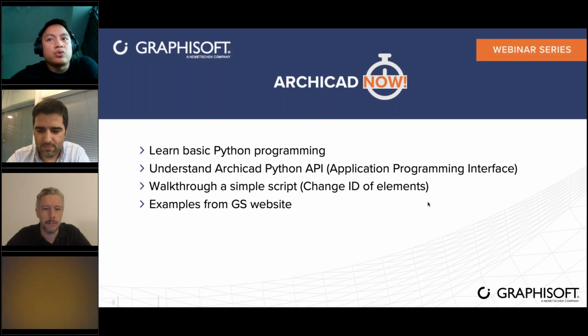We're not going to go through all the functions, commands, types and utilities in the Archicad API libraries, but I'll show you some easy commands and functions, for example how to get the element. Don't worry, we will share the link in the slides where you can find all the documentation for the API. The focus of my presentation is mainly what Archicad Python can do, and how the Archicad Python API could help you in your daily work. I will walk through a simple script, which is how to change the ID.